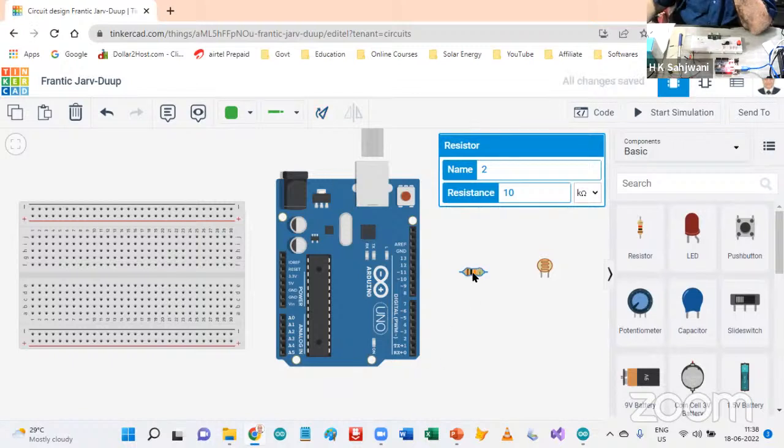So once these two things are connected in series, say suppose I connect it to this point, then whatever voltage we apply across from this point to this point will be divided among this resistance and this resistance. Therefore, if you allow the light to fall on this, its resistance will change, but this resistance will not change.